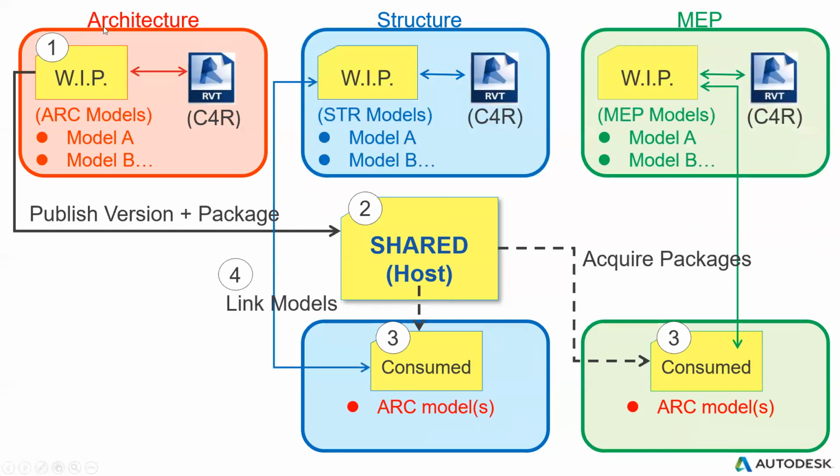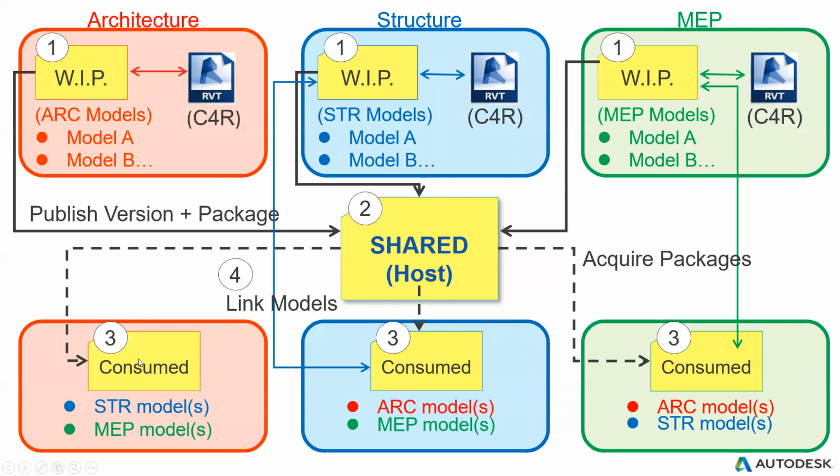So maybe 2 months later, the structural team and MEP team work on their WIP model based on the architectural model, and this time they can publish the share package in the BIM 360 platform. And the architectural team right now have the structural and MEP models inside their own consume folder, and then link back to their own work in progress model.